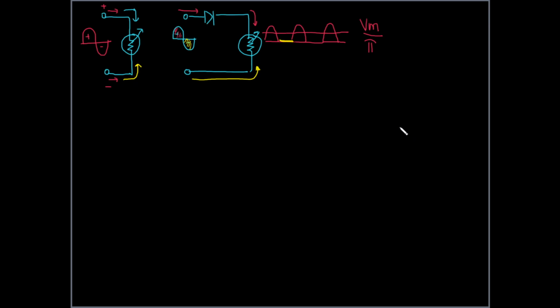There. We actually had a computation in your module. I hope you have read your module already. A 10 volt RMS AC voltage is only going to be interpreted by this meter movement to be 4.5, which now leads us to the conclusion that the AC sensitivity is only 45% of the DC sensitivity.